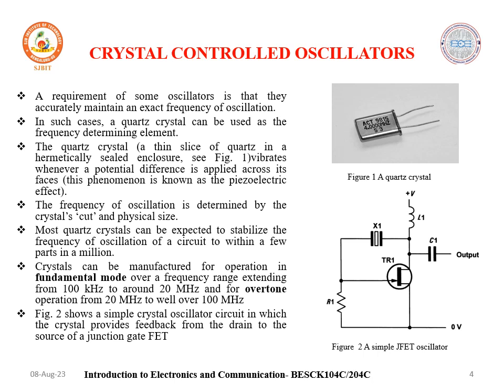vibrates whenever a potential difference is applied across its faces. This phenomenon is called the piezoelectric effect. The frequency of oscillation is exactly equal to the resonant frequency of the crystal. The piezoelectric effect is an effect in which, when a voltage source is applied across it, it will change shape and produce mechanical forces, and the mechanical forces revert back and produce electrical charge.